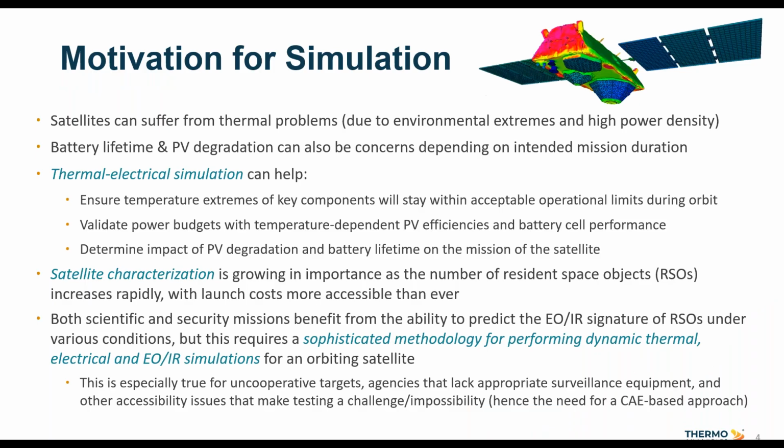Okay, so there's a variety of motivations for performing this sort of satellite simulation. Starting on the thermal side of things, satellites can suffer from thermal problems due to the extremes of the environment that they're in, as well as the high power density of their design with all the electronic components being packed on the inside and outside. Additionally, the lifetime of the battery pack and the degradation of the solar panel over time can both be concerns depending on the intended duration of the mission.